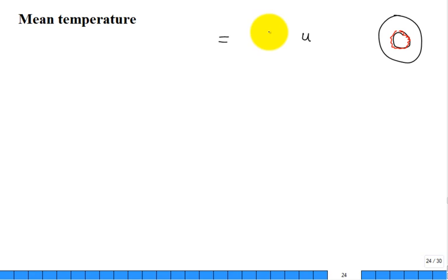So then I have the velocity times the little dA. What does that give me? A volumetric flow rate. What was my dA again? 2 pi r dr. All right. So I have my volumetric flow rate. I multiply by rho. Isn't that my mass flow rate?